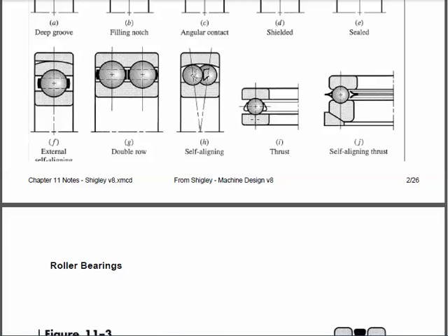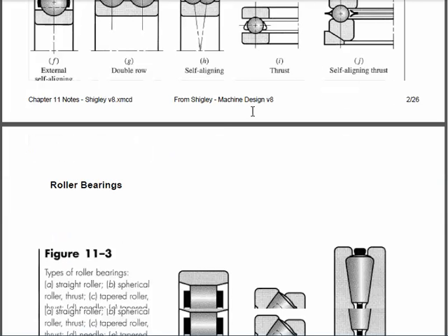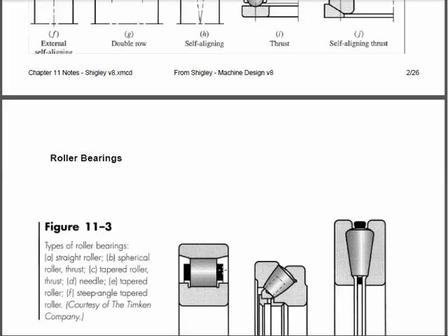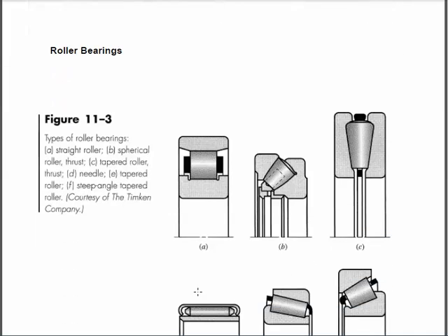Now, we've studied Hertzian contact stresses and such, and we know that they'll deform so that there will be a finite area of contact between a ball and a flat plate after deformation, but mathematically it's a point. Okay? For a cylinder touching a flat surface, mathematically the region of contact is a straight line. And of course that still doesn't have any area, but a straight line is infinitely bigger than a point. And a straight line under Hertzian contact stresses will produce a larger area of contact, therefore heavier loads for the same stresses, those kinds of things.